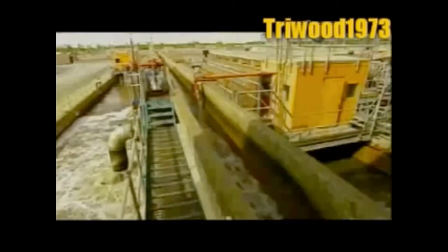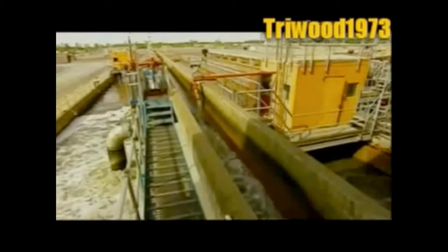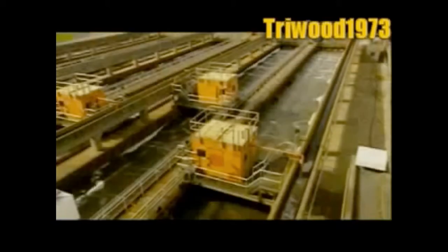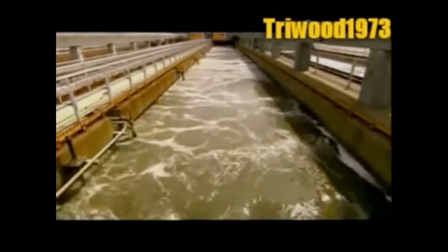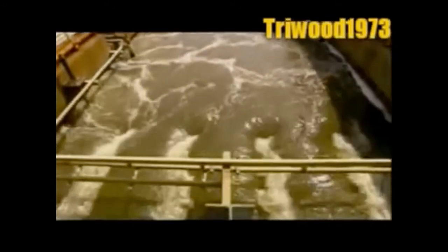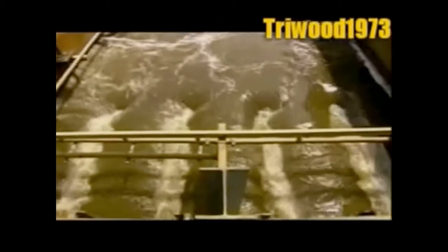Giant presses compact this rubbish, squeezing out the excess water. Trucks then haul the stuff to a landfill, where it's buried. The wastewater meanwhile flows into large tanks called grit chambers. Grit refers to the particles in the water, such as gravel, that are inorganic, meaning they don't decompose or burn. These particles, some as tiny as a grain of sand, gradually settle to the bottom. Then they're pumped out and trucked to the landfill.